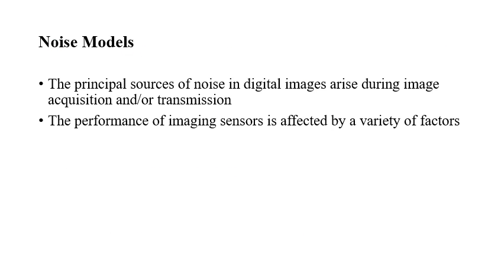So the main focus of today's lecture will be on the various noise models. Unless we know the various noise models, we cannot design the restoration filter, or understand how the degradation function h has been arrived at. Your restoration function should be the inverse of the degradation function, so that f cap of x comma y will be a proper estimate of f of x comma y. Did you realize that? It should be, right? In order to go for the restoration, we should understand how the degradation process took place. So here we need to understand the various noise models.